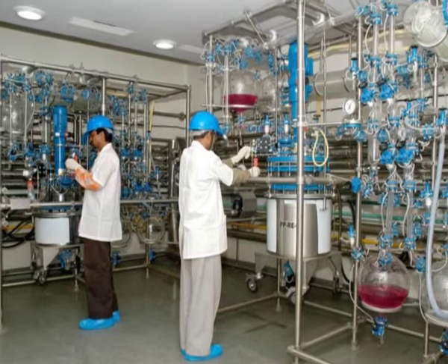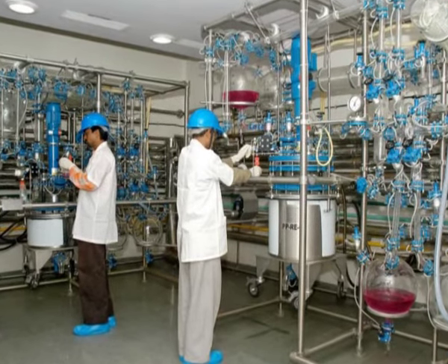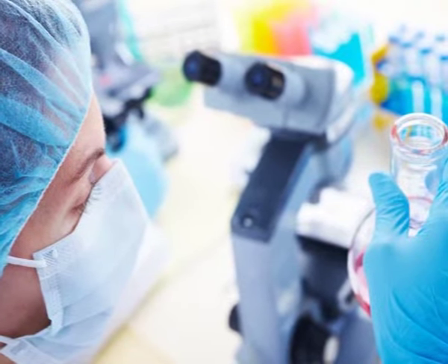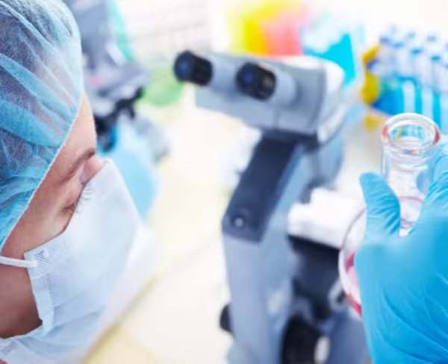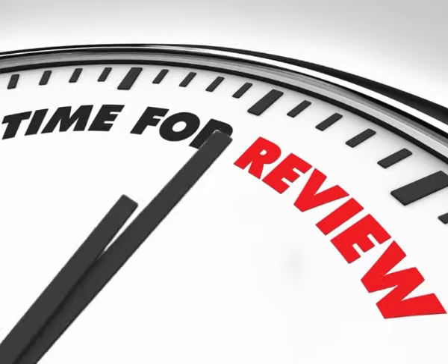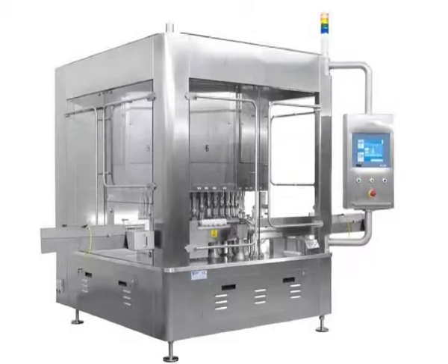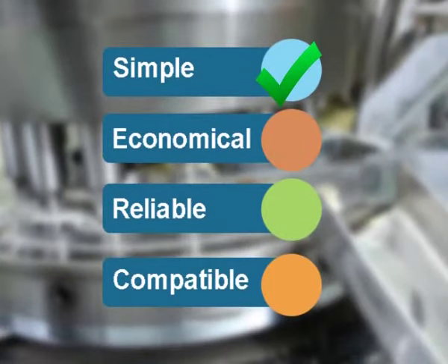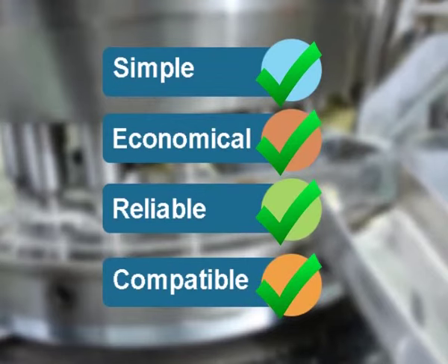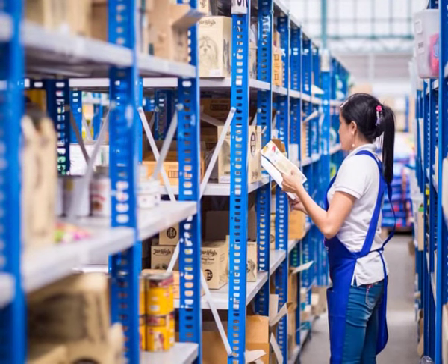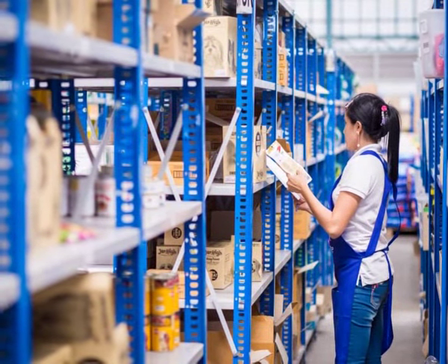After having a brief idea about pilot plant studies, let us understand that it is at this stage that a close examination of the formula is done to determine its ability to withstand the batch scale and process modification. It then reviews a range of relevant equipments to determine the most simple, economical, reliable and compatible equipment during processing. It allows checking of the availability of raw materials that consistently meet the specifications.